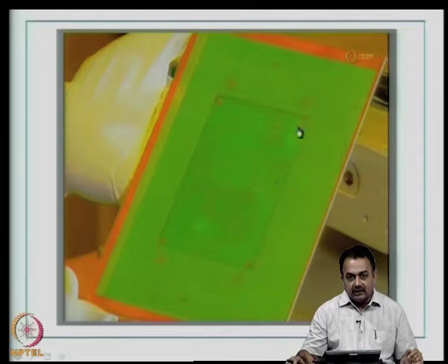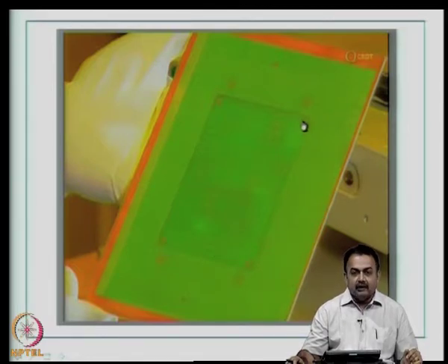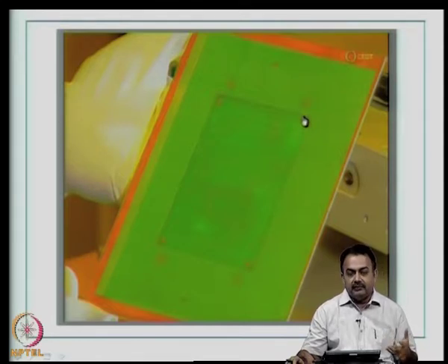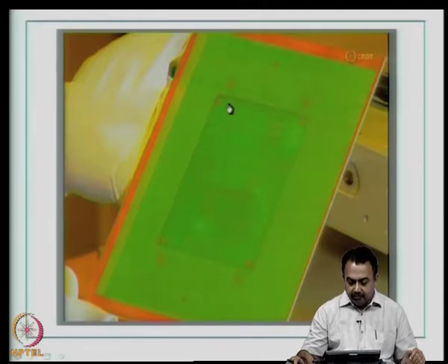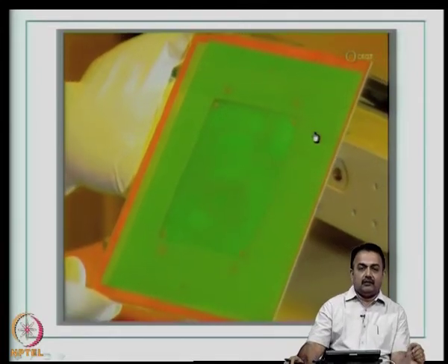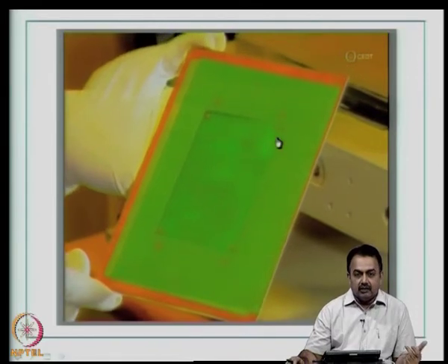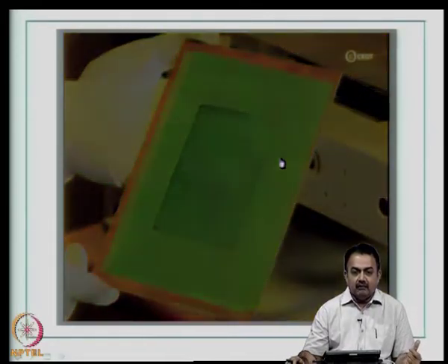Now, you are going to use a mask for the solder mask after this material has been cured in the oven at, let us say, 100 degrees centigrade for about 10 to 15 minutes. Now, you can place a solder mask photo tool and then open up the unwanted areas and remove it by developing. So, the pads, or the pads and tracks, will be open; other than the pads, all other areas will be covered with the solder mask material. So, this screen printing is very useful for the print and etch process, a solder mask process, or legend printing for printed wiring boards.